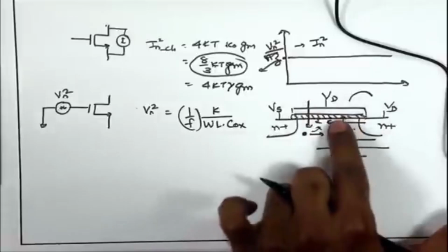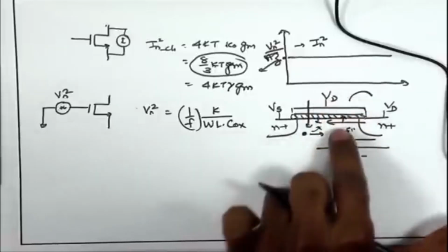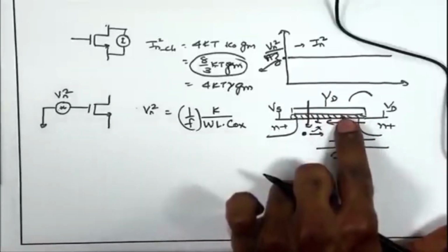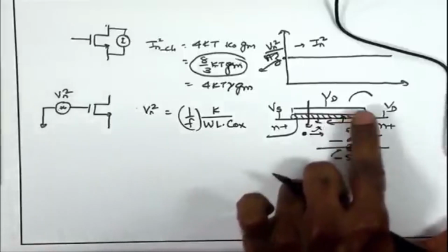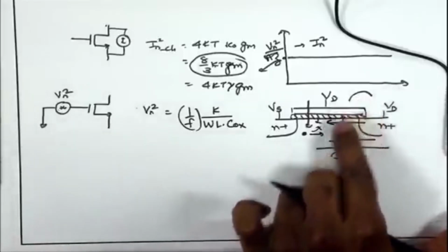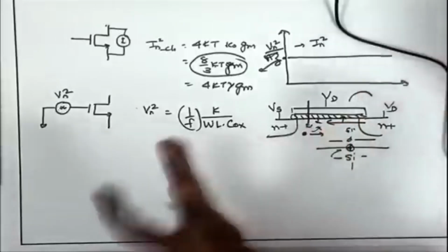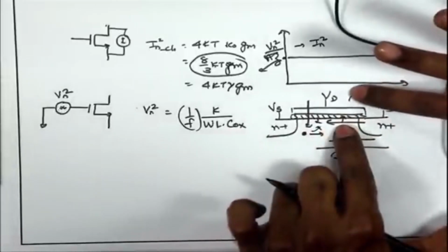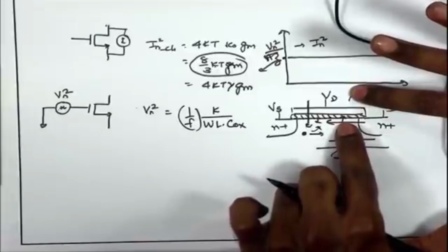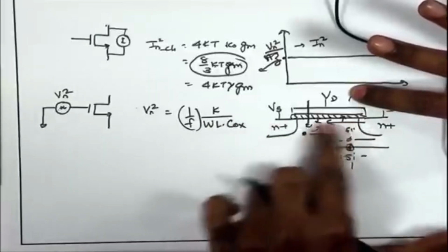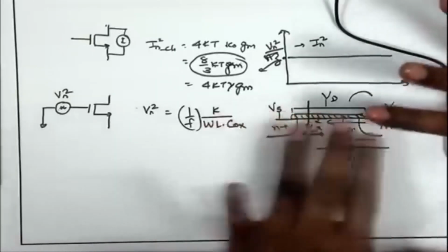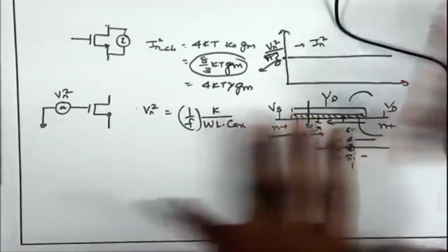and it is able to introduce more noise. Whereas, if the signal at the gate is changing much faster, as compared to that, this trapping detrapping phenomena is slower, so that it is not overlapping with, or is not really aligned with, the frequency of the signal. So, this is shifting at lower frequency. So, lower is the frequency, larger is this overall integrated trapping detrapping phenomena.